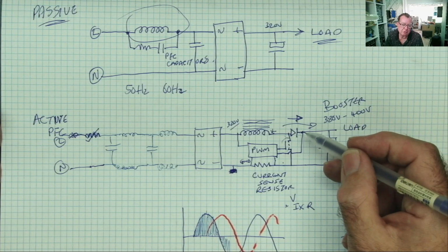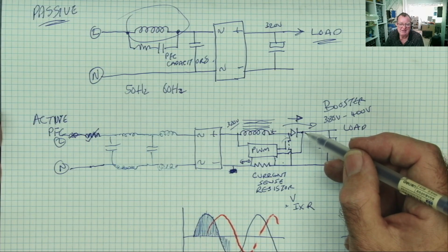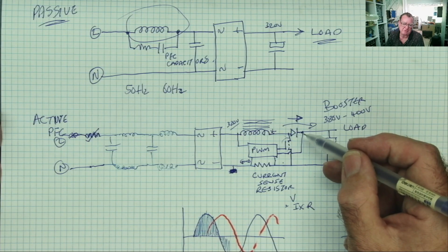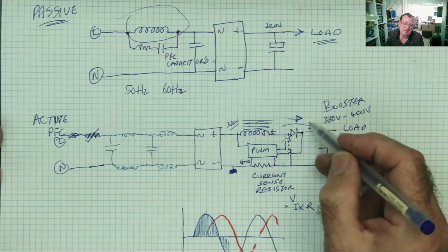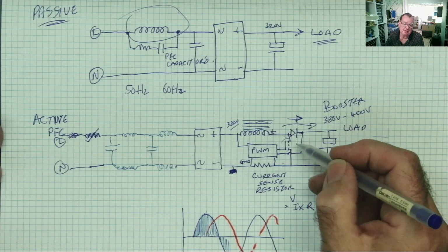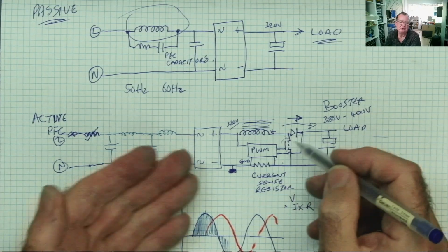This diode could go short, it could go open. In honesty, that's something I haven't particularly seen. I think I have seen them short, but it's not common, so bear in mind we need, in this case, to test the diode, we need to test the MOSFET. So that's the initial checks with this.